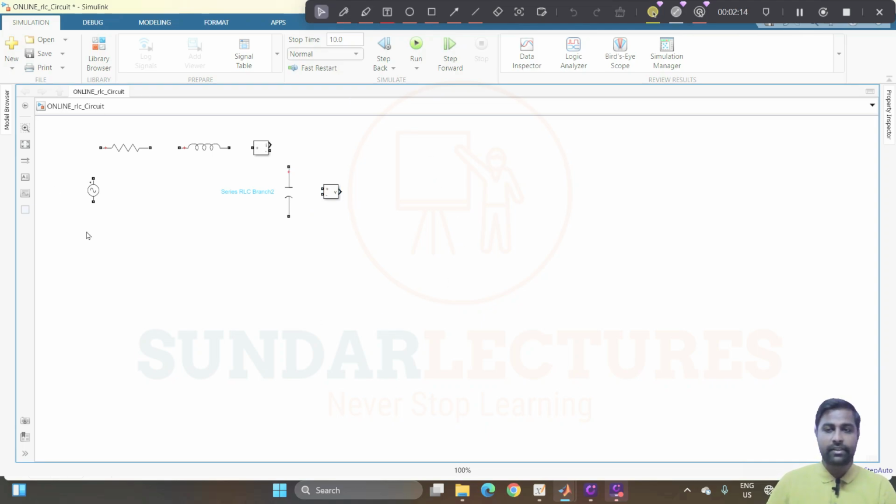Now we have got everything, so try to connect this diagram. The input we connect in series. So it will be connected, and this has to be connected, and this will be connected. The current measurement is connected in series because we are going to get I of t, and I of t in a series circuit is the same in all the elements. There is no difference. But V of t is nothing but the voltage across the capacitor, right? So you need to connect this across the capacitor, this one as well as this one.